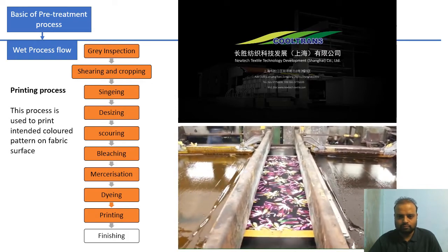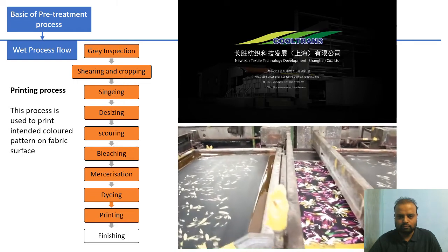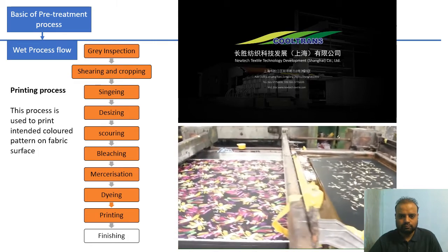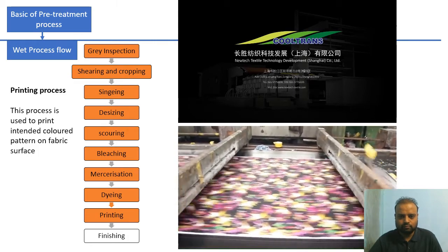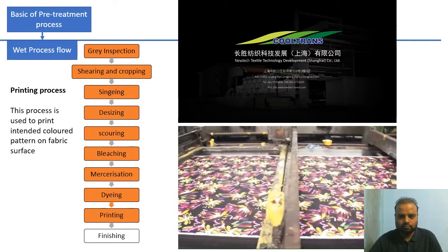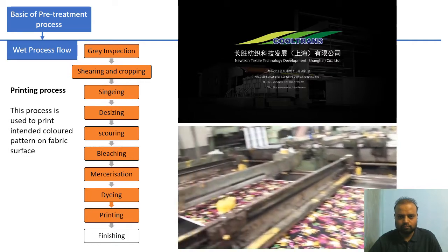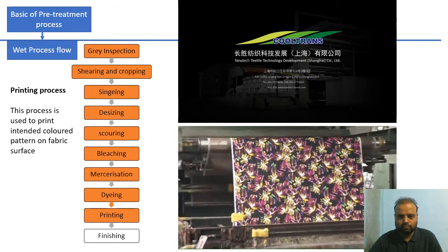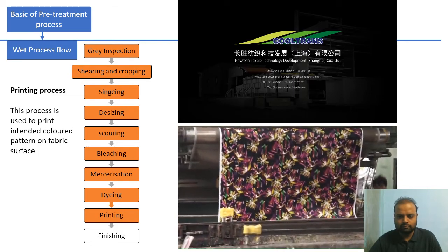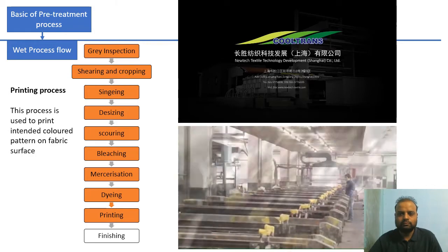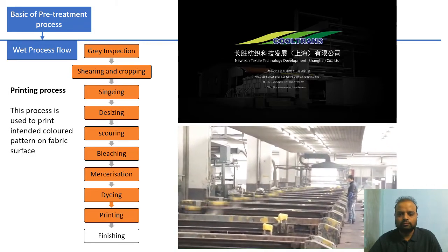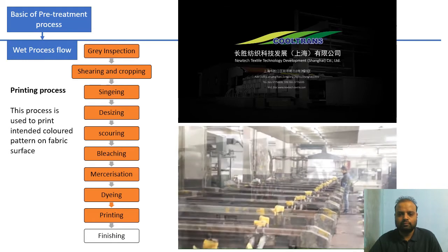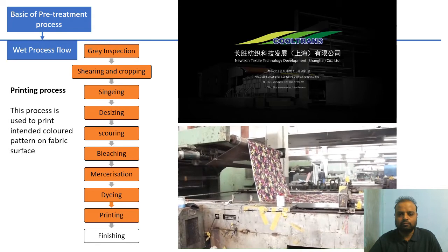At this point, all 10 screens have been printed on the fabric: light and dark pink, light, medium, and dark green, light and dark purple, red, and light and dark yellow. The print has a total of 10 printed colors plus the white ground for a total of 11 colors. This machine can print up to 16 colors, and the bed of the machine is very long. For flatbed printing, the longer the machine, the more colors you can print.